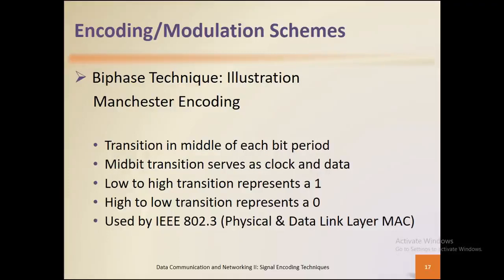So once again, clocking is quite essential. Error detection, congestion, all of these that impede signal transmissions are well addressed within the biphase technique. Even though it's quite efficient at the data communication level, or just the data transmission level, it also does have some issues. So it's not perfect, but at least it guarantees better transmission as compared to the other two, the non-return to zero or the multi-level binary techniques.